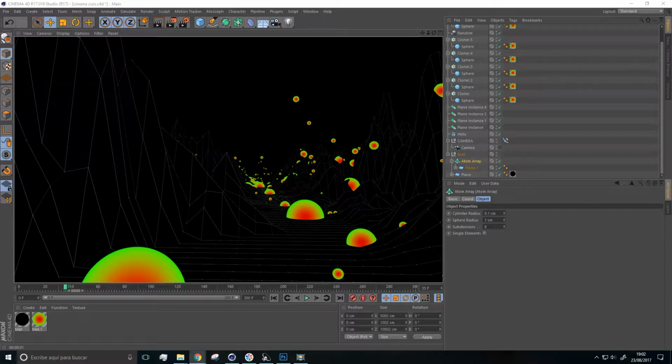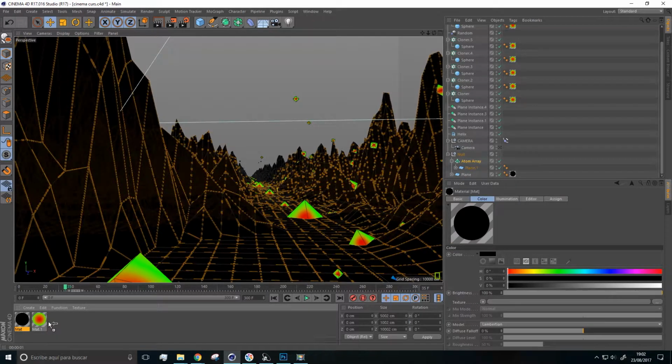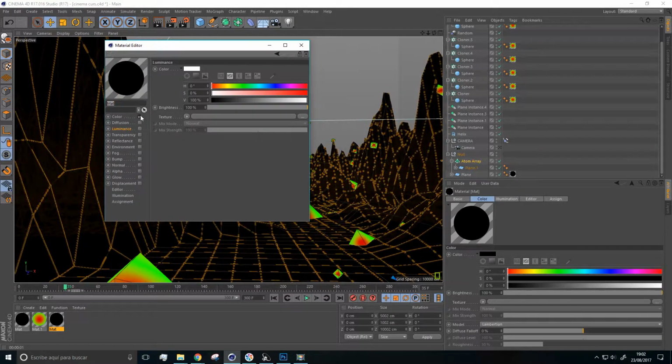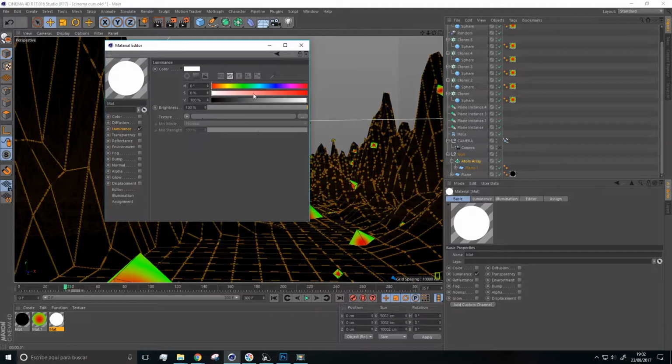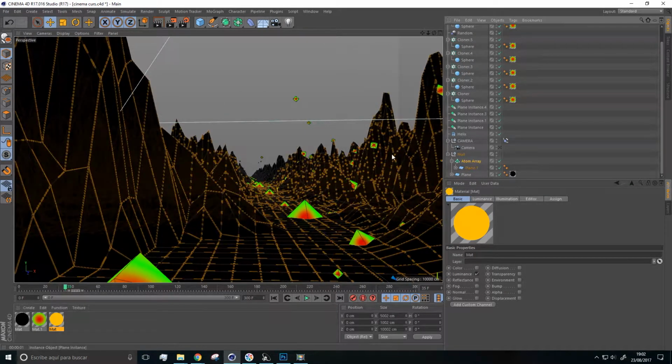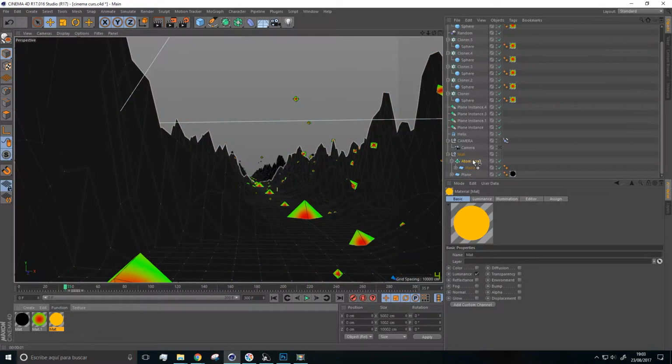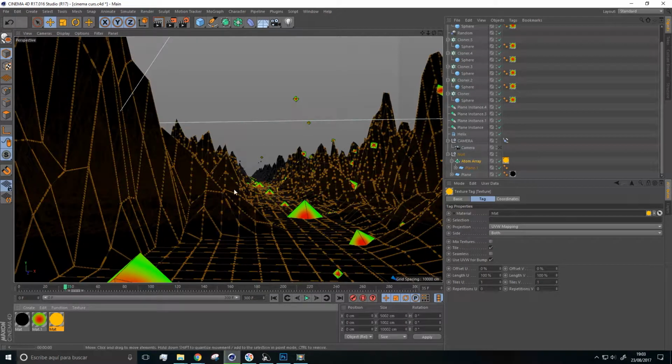We can also add color to this, obviously. So select this material here, Control to copy it, or to duplicate it. In the panel, uncheck the color and select luminance. Let's give it a green color. Or maybe blue or yellow. Actually, let's go with yellow. Okay, place the color here in Atom, and you see the color is applied.